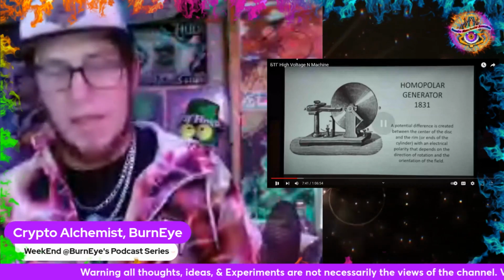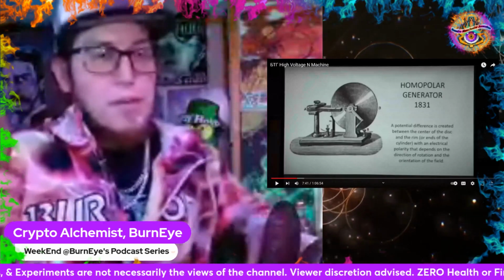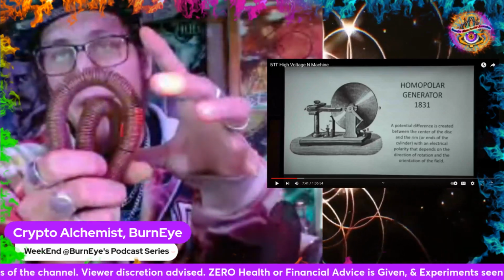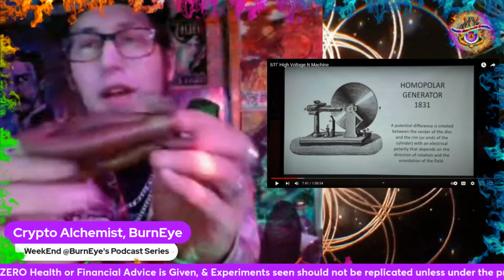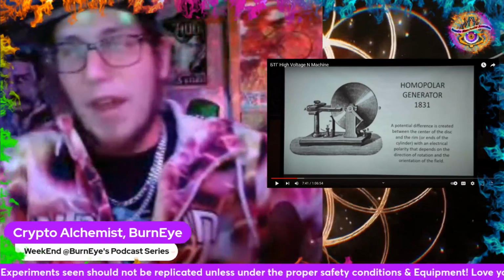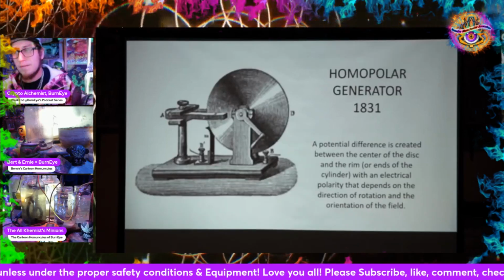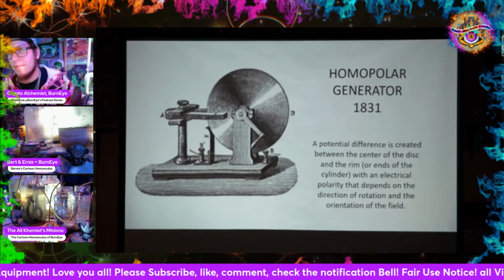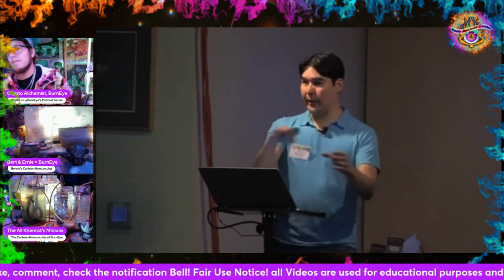So that's exactly what Aaron's talking about there. For a coil, you put a magnet through it, which would create an EM field. Or if you connect current into the coil, then the coil creates its own electromagnetic field from that. But the main point is that the conductor, the copper wire for example, and the magnet always have to be moving independently of each other, in whatever frame of reference. They have to be moving like this.